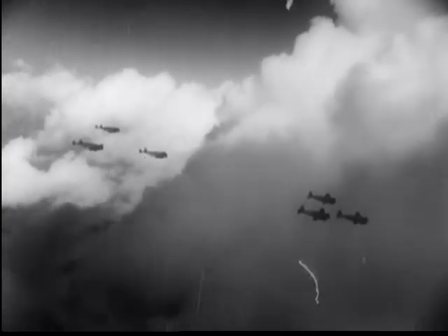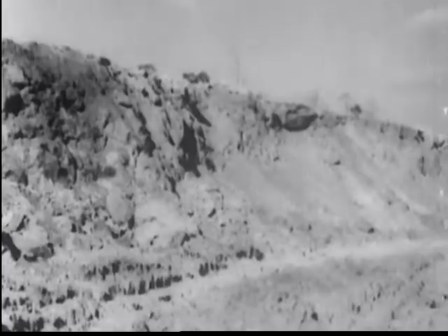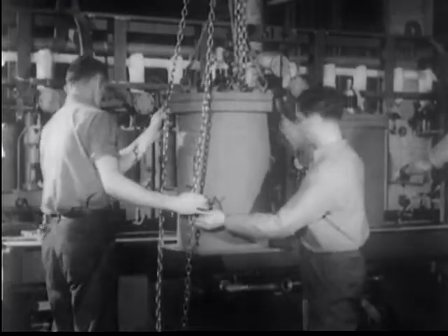Electronic rectification is also helping to build American air power by making available record-breaking quantities of aluminum for plane construction. From Arkansas mud to American air power involves a complicated conversion of material. Before pure aluminum can be extracted from this bauxite ore, direct current must be applied in a vital reduction process. To obtain that direct current from AC transmission lines, the ignitron rectifier is used.